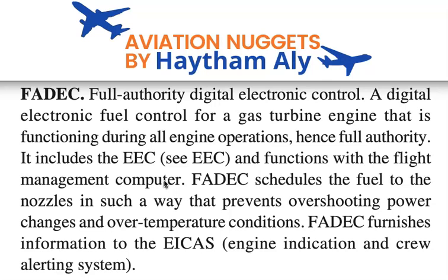The FADEC schedules the fuel to the nozzle in such a way that prevents overshooting power change and over temperature, so that the FADEC protects against overspeed and over temperature, protects against high RPM N1 and N2, and protects against excess EGT. And finally, the FADEC furnishes information to the EICAS, which is the engine indication and crew alerting system.